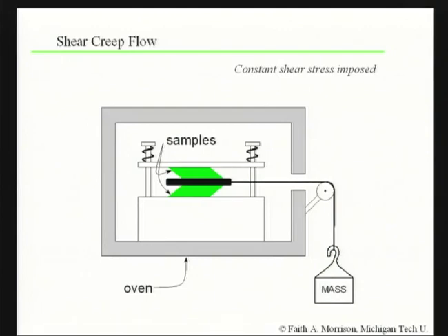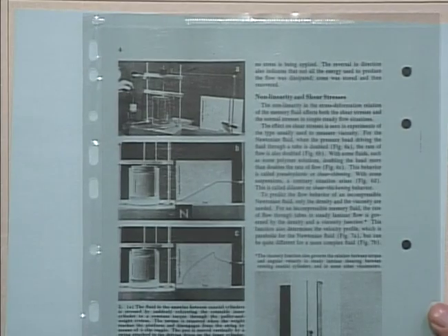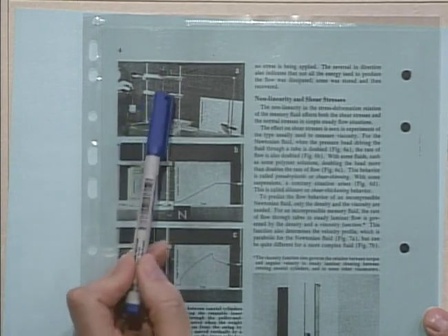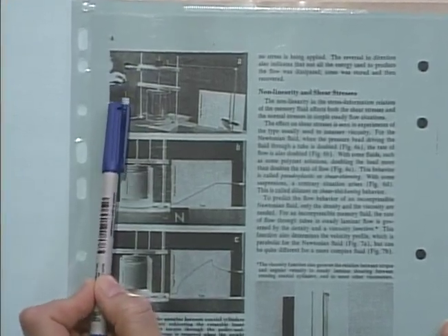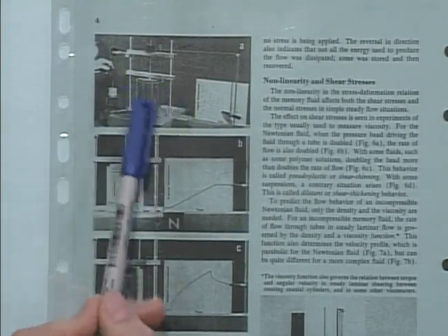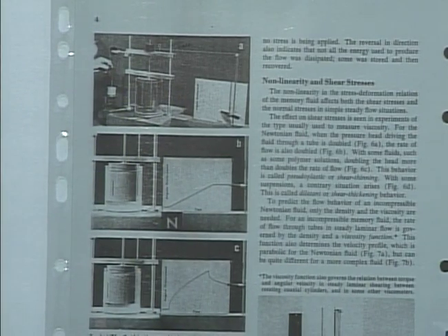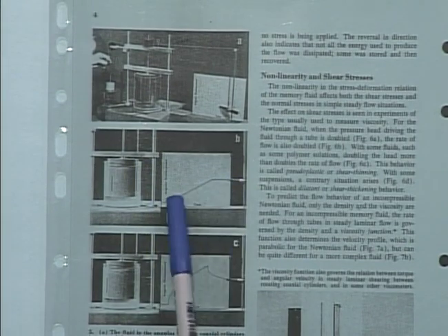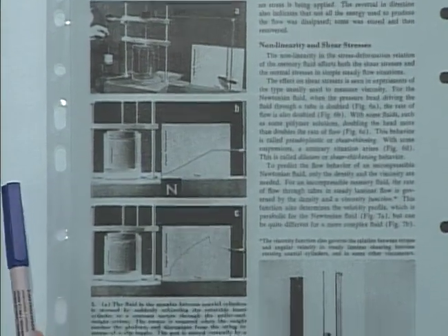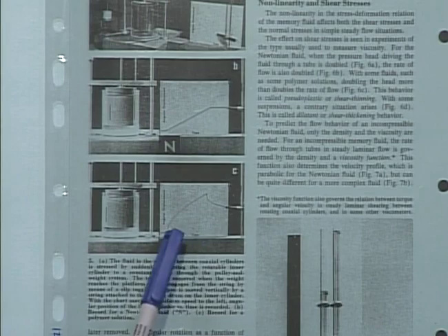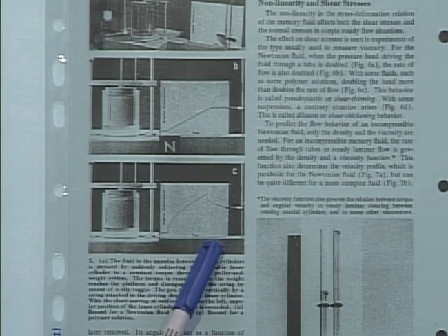And in a torsional flow, as I said, we saw in the movie a kind of a creep flow when he showed these concentric cylinders here, and he had a nice complex weight over here on the left-hand side that was pulling down, and then he was using it to torsionally drive this flow around in a circle. Okay, so we're going to see now a material function that looks like this Newtonian one that goes up like that, and this non-Newtonian displacement of the cylinder. This is going to be related to strain as opposed to strain rate.